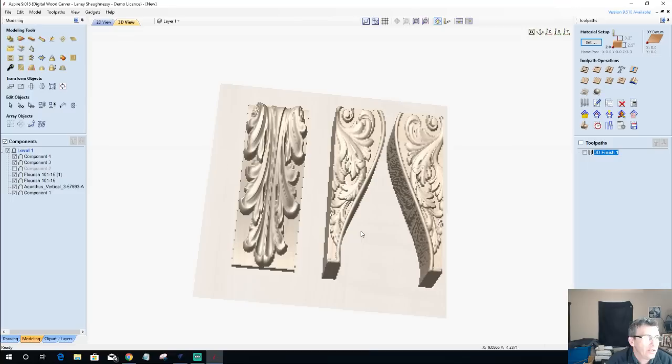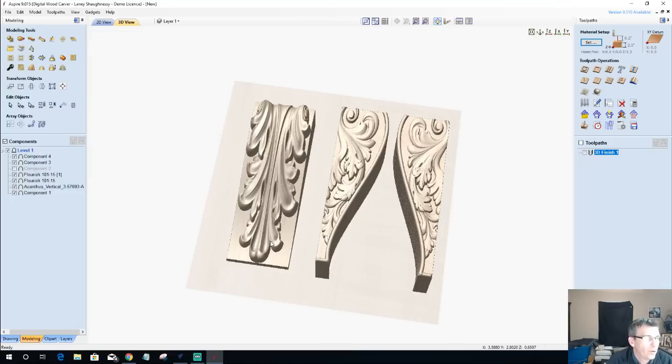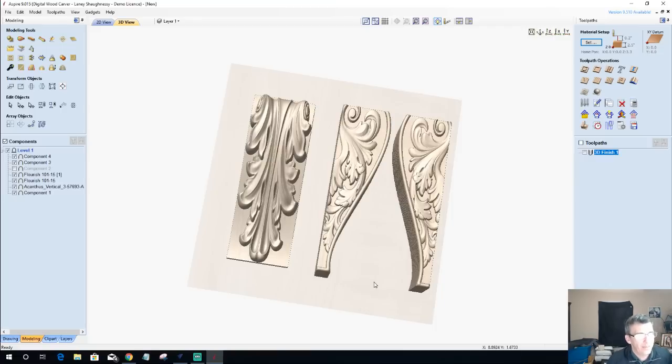But all I wanted to do, imagine if you were looking from the front of the corbel and the sides of the corbel, this would be the overall design on the front and the sides. Now, we're still kind of in the debate of, do we cut the side pieces, since they've got to be trimmed down from the back end? Do we cut them out of this 2.5-inch piece, or do we just take what we have and copy it over into a new project file and create these two parts? Or four parts if we're making a set of shelf corbels, right? We're going to have double of everything that you see here.